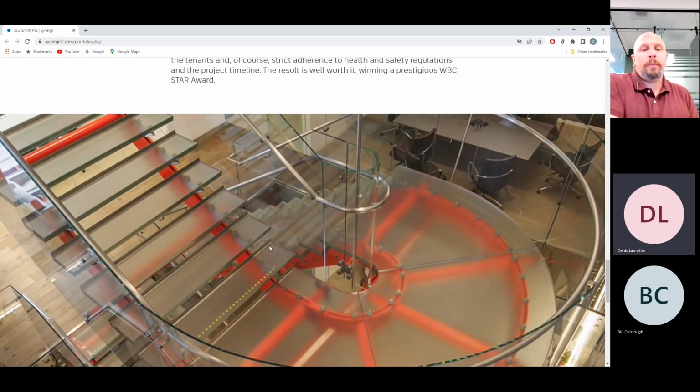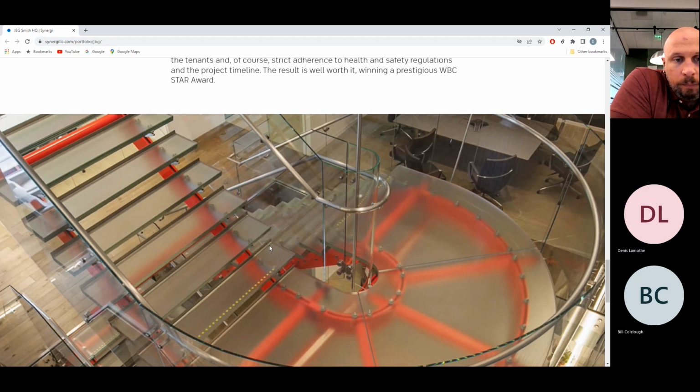So we don't typically, with the exception maybe of an HSS tubing, choose the profile; generally the architect will specify it for us. They may have a very specific need for why they want a profile used. If the engineering that we do on the stair says that we can't use that profile, then we may propose an alternative. But ultimately, I'd say for most of our projects, the stringer type is chosen for us, and we go with whatever the architect and their engineer decided was needed for their project requirement.